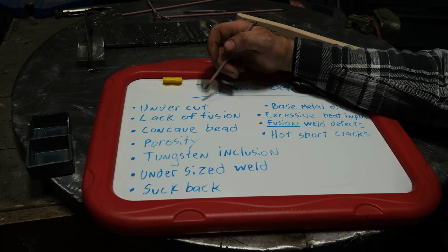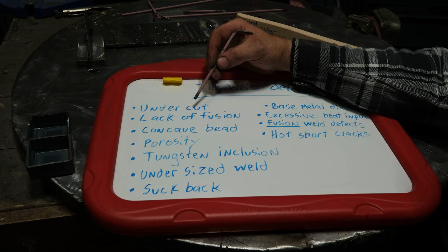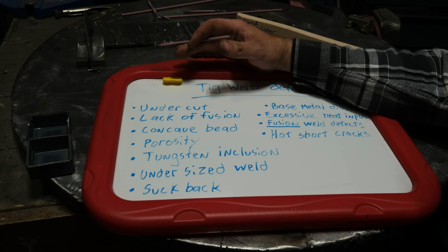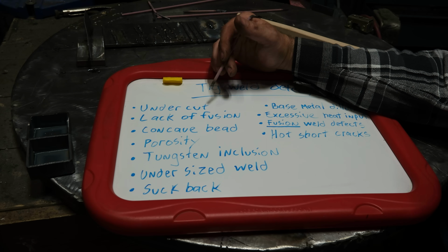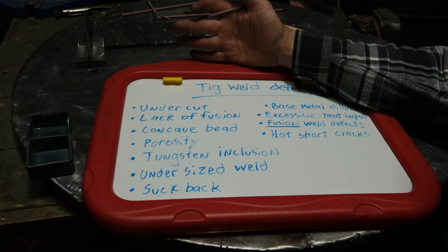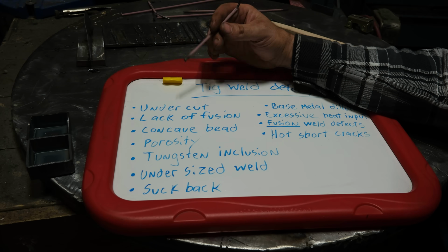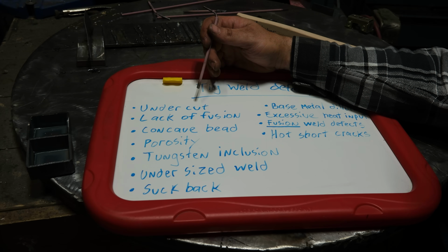Now, when you're welding things like tool steels, chromoly, and all sorts of other non-mild steels, forgings especially, you're going to find that undercut is far more prevalent on things other than mild steel with TIG, and there are ways around it. In this video, I'm not going to be covering how to weld those types of steels without undercut, but I just want to make you aware that the type of material you're welding on definitely plays a huge role in how easy it is to undercut it. The thickness of the material that you weld also plays a role.